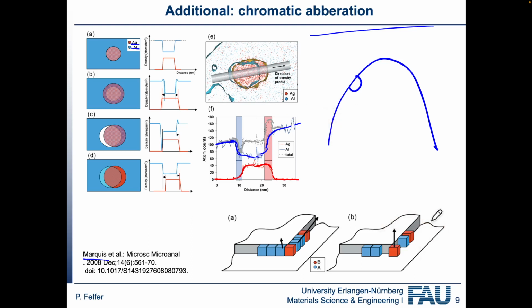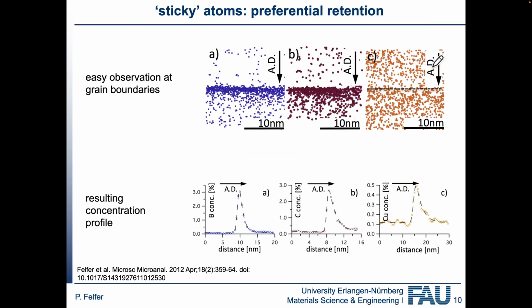This typically is most prominent at relatively small precipitates. There is no scale bar here, but this would be roughly around 10 nanometers, or thereabouts. So relatively small precipitates, but not super small, a typical size order that we look at. And this is still in XY, meaning the curvature of the tip. But we also get some deviations in Z, and this is what's called preferential retention,